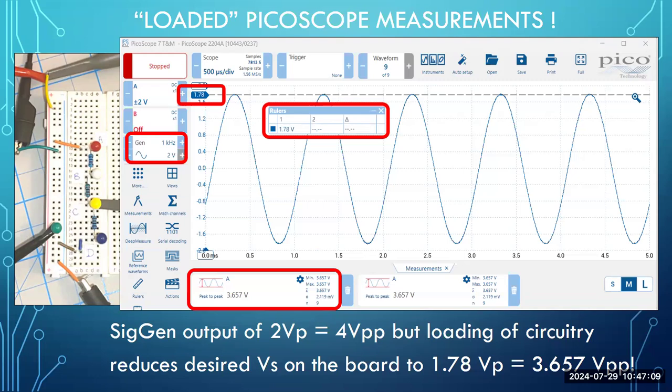And that's called loading. Okay, so the loading is a physical connection, and the loading effect is that this physical connection of these resistors does draw current, and as it draws current, if the power supply of the signal generator is not high current enough to be able to keep things stable, then we're going to see a little sagging.